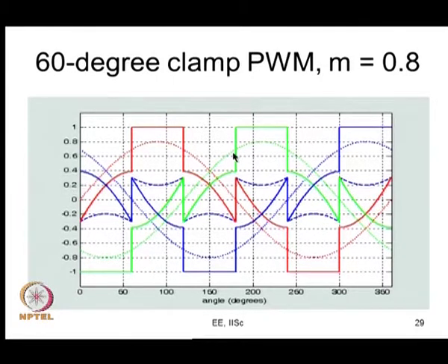So, one wonders how will dead time affect here, what is the significant difference between here and there. Now, the PWM signal you see it is clamped. Earlier when we saw the error voltage did not really depend on the duty ratio, whether the duty ratio of the phase was 0.7 or 0.8 did not matter. Again, whether the current was 10 ampere or 15 ampere did not matter, what only mattered was the direction of current. The direction of current determined the sign of error voltage, and what was that error voltage? The magnitude of the error voltage was determined by the DC bus voltage, the dead time and the switching frequency. So, these are the ones that determine here.